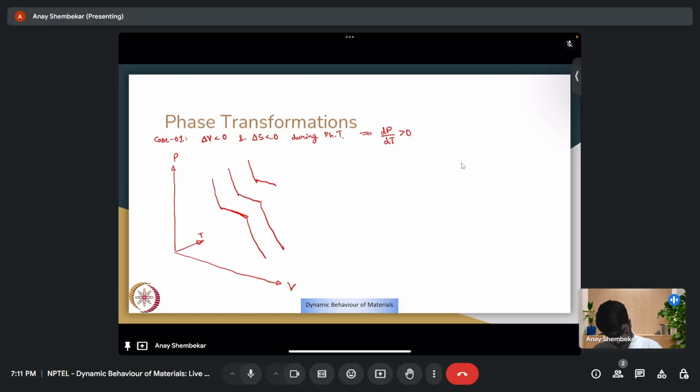These straight lines that I'm drawing are basically each isotherm, which you can think of as plotted along a temperature cross section, and then it is plotted on the PV plane. So I just shade this two phase region. This is my two phase region. Both phases can simultaneously exist.